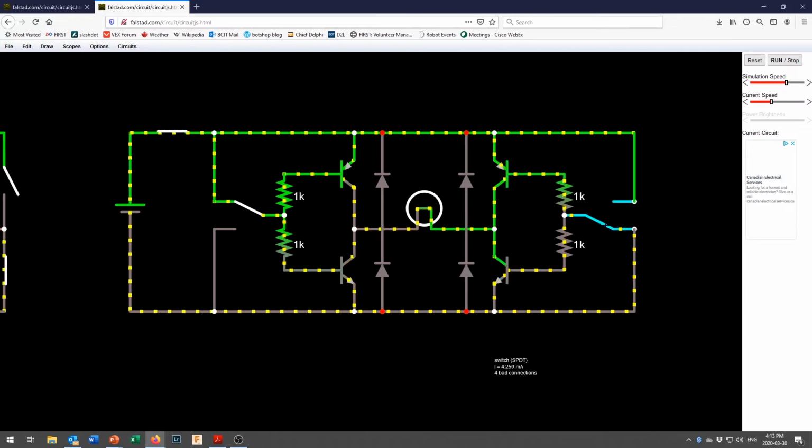Because sometimes when you slam that motor into a stop, because of that inductive freight train effect of all of the stored energy in the spinning motor and in the magnetic field about the coils, that will come to a sudden stop, causing a sudden voltage spike in this side that can either drive it up higher than your battery voltage, in which case, instead of it going into your transistors, that voltage spike comes back here and gets absorbed by your batteries, or it can suck that voltage down, in which case this line would drop below 0 volts, causing a big problem right here.